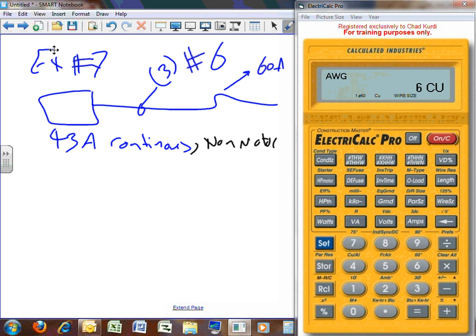Put this in your mind. I threw this one in front of you because whatever you come up with after you derate, guess what? You're not going to be using less than number 6 anyway. So let's go ahead. Everybody got that one? No matter what we come up with when we derate right now, I shall not use less than number 6, because that's the normal condition. Okay, let's go put ourselves in Arizona at 50 degrees Celsius. Problem with that? Typical.